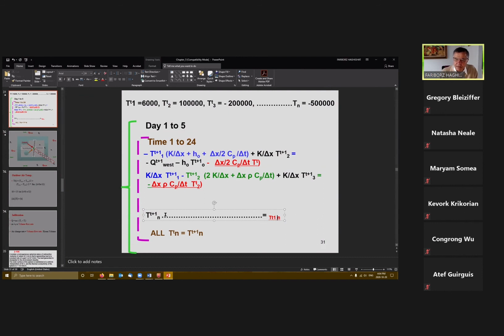All of them in this one, okay? You keep the old temperature, because when you're going to the next time, you need to know the previous temperature. Therefore, you put the temperature at 2 o'clock here, and then you go calculate the 3 o'clock. When you go to 3 o'clock, you need the temperature at 2 o'clock. This temperature is 2 o'clock, okay? Now, this was what you're doing for 1 day. It's exactly the same as before. But the only thing is that at every time you keep a record of all the previous temperatures. Is it clear here?